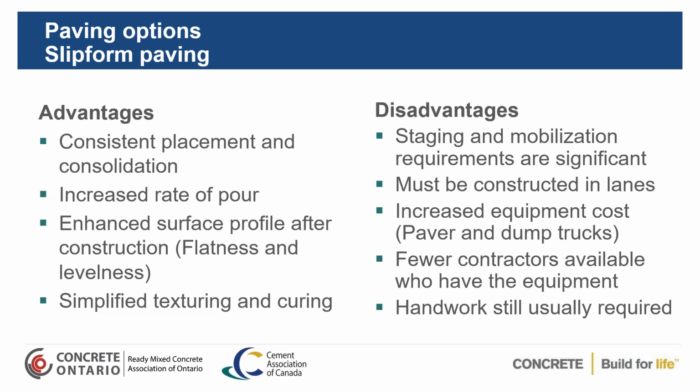Your disadvantages are your staging and mobilization requirements are certainly significant because of the equipment that you're bringing on. You must be constructed in lanes because you're paving with the machine. You also have to do handwork. If there's areas where you have islands that have different configurations, then you'll have to do some handwork on this as well.